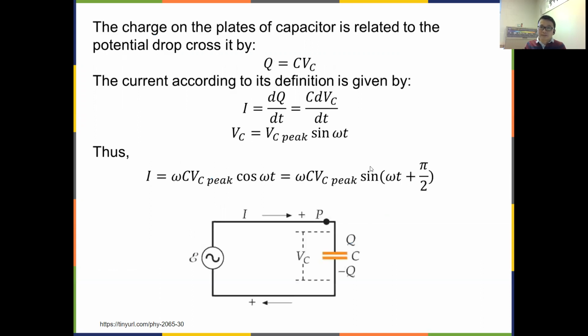Okay, now let's turn to a capacitor in the AC circuit. For a capacitor, when you charge it, remember when you have the switch on an RC circuit, the voltage starts to build up, but the current goes down. So if your voltage is a sine function like this.